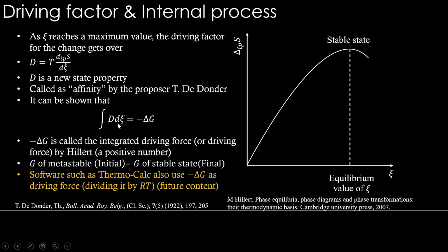It can be shown that the integration of D dξ is equal to minus delta G. Minus delta G is nothing but the reverse of the driving force that we have been talking about. This minus delta G is called the integrated driving force, or driving force, by Hillert, and this is treated as a positive number now.